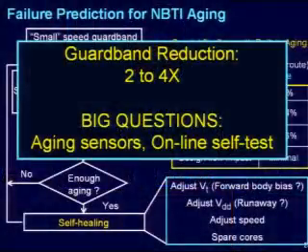Okay, so the costs of putting these sensors, so we'll have special flip-flops as I will show next with built-in aging sensors. As you can see again, the costs are very small for doing something like this. And oh, by the way, a lot of people have suggested using ring oscillators and so on to collect this aging data. That's not very scalable because ring oscillators' activity factors are very different from the activity factors or the signal probabilities of your actual design, and they may not even show up the same way basically. So a ring oscillator may or may not age as much as your actual design. So what you want to do is you want your actual design to tell you how much it has aged, and that's what you can do with these circuit failure prediction techniques.